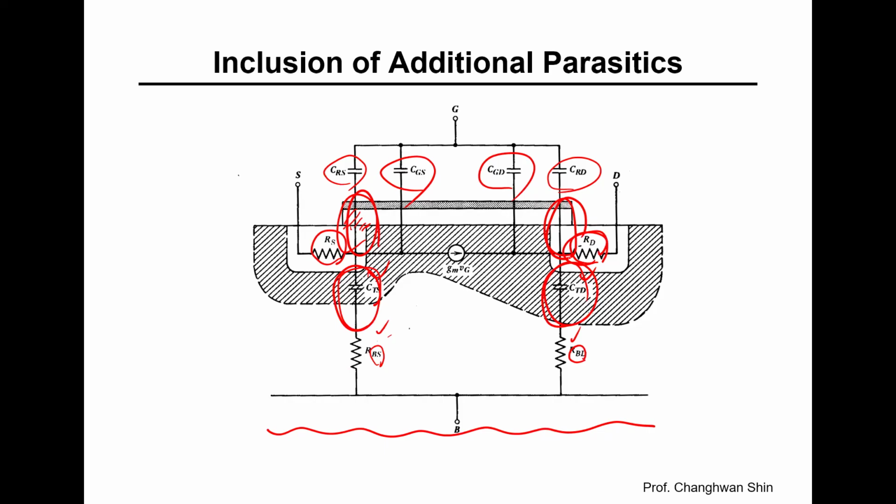So at much lower frequencies, many of these parasitics can be ignored. Okay, if the MOSFET is working at low frequency, many of these parasitics that I have just mentioned can be completely ignored. However, they become dominant limits at high frequency. The gate capacitance, for example, slows down switching speeds as it must be charged and discharged during transitions, which is like how a heavy steering wheel makes a car less responsive to quick directional changes.